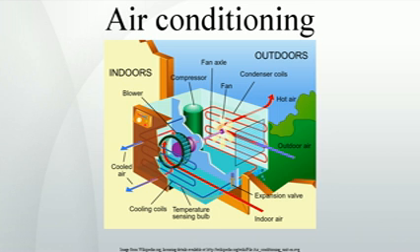Reducing climate change impact is an important area of innovation because, in addition to greenhouse gas emissions associated with energy use, CFCs, HCFCs, and HFCs are, themselves, potent greenhouse gases when leaked to the atmosphere. For example, R22, also known as HCFC-22, has a global warming potential about 1,800 times higher than CO2. As an alternative to conventional refrigerants, natural alternatives, such as carbon dioxide, CO2, R744, have been proposed.